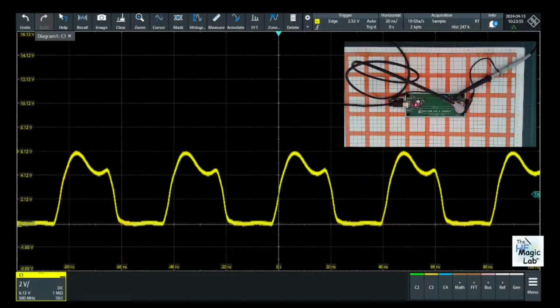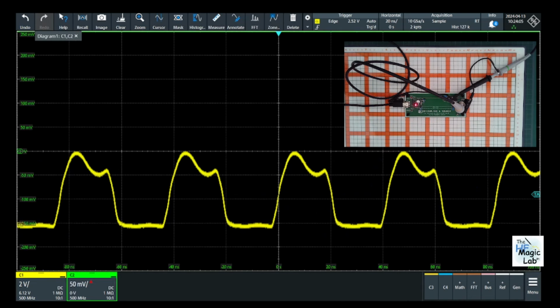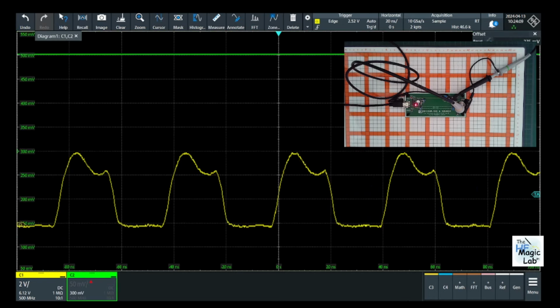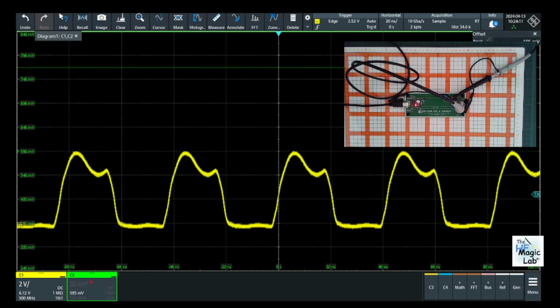We switch to the other screen, and you can see this clock signal that is clearly distorted, and we are going to activate channel number 2 in my Rohde & Schwarz oscilloscope so we can see how is the voltage drop, the ripple in the power supply line.